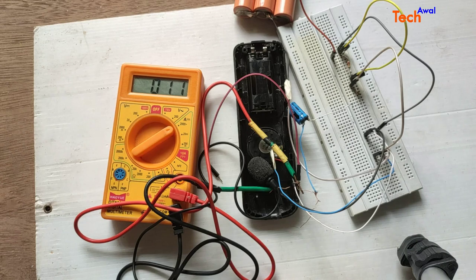When the capacitor is charging, at the initial phase there will be maximum current, that is 11 microampere, and it will decrease. So it will come to 10 microampere. Then suddenly it will start discharging in reverse. Now it is positive current. Okay, it reached minus 9.